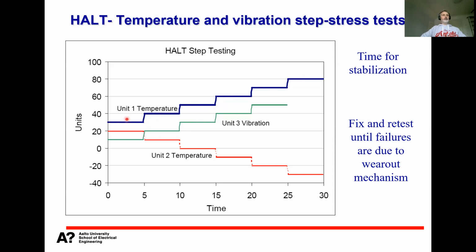The same for low temperatures. So you start again from some temperature, then you go 10 degrees below, you go to 0, you go to -10, -20, and if you find a failure here, you fix it. Let's say you select another component which withstands the cold temperature better, you select a new material which does not become brittle at that temperature or whatever.